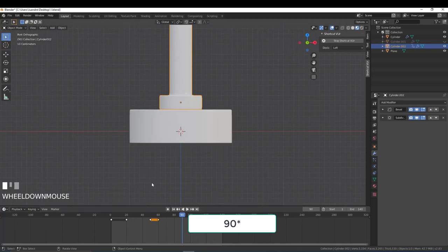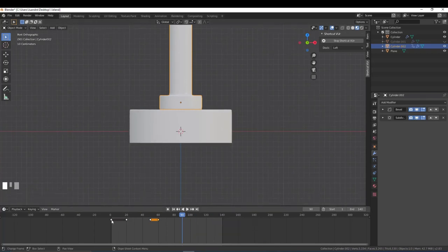But an easy way to get it back to its original location is to click on the first frame here, then go Shift D and just slide this keyframe or this marker all the way to frame 90. And then click to let go. Now what's going to happen is we're going to have a bit of a hold. And then it's going to come down. In frame 50, it touches down. There's a quick hold and then it comes back up here.